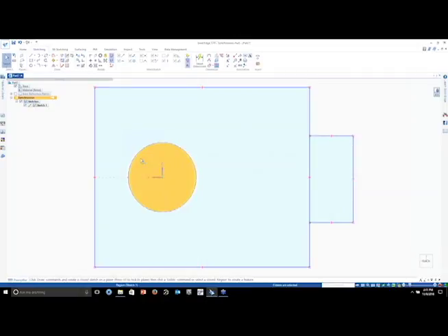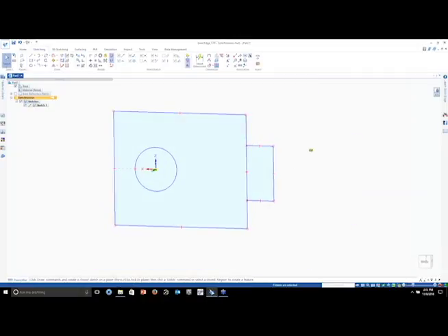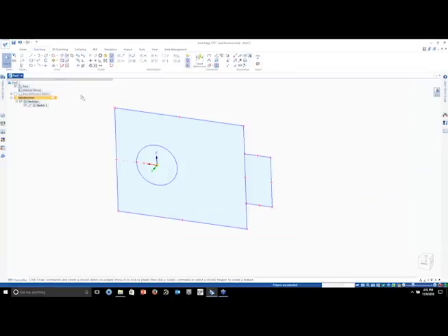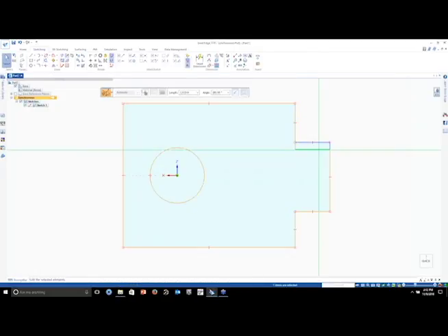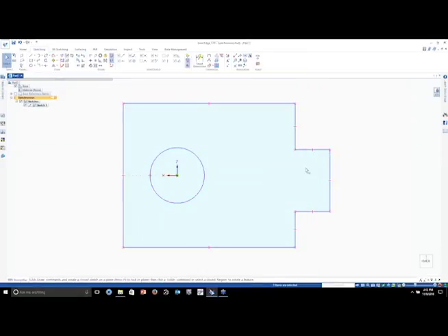I can say, position my steering wheel from where I want to go from, and I'm just using the little ball in the middle to position. So I just snap over to an edge, it snaps to the center, grab that little blue disc in the middle. So you got the ball, you got the torus, and in between you got this little disc plane. And that allows you to kind of move things 360 degrees in space. I'm going to come over here and attach it to that piece of geometry right there. So now I'm centered on my reference planes. Typically, you want to go ahead and use reference planes for symmetry reasons, for dimensioning reasons. It's just good practice.